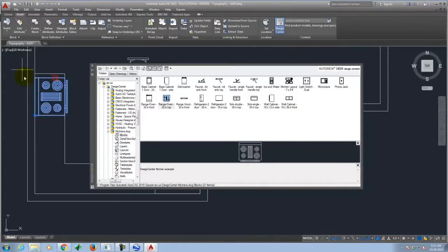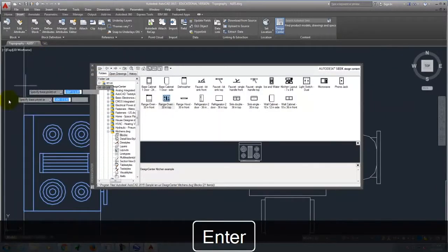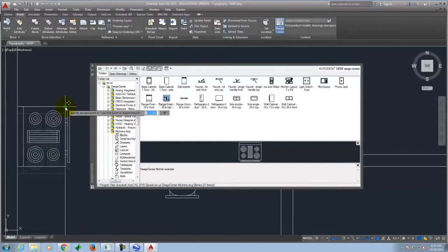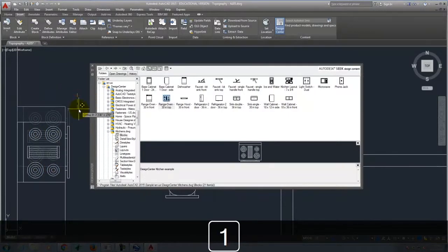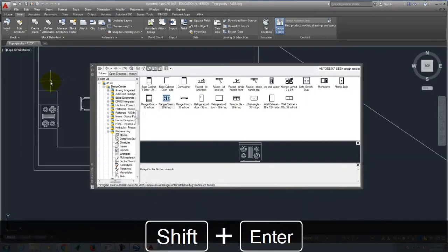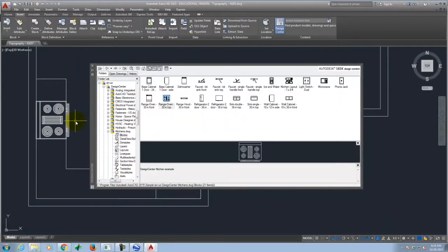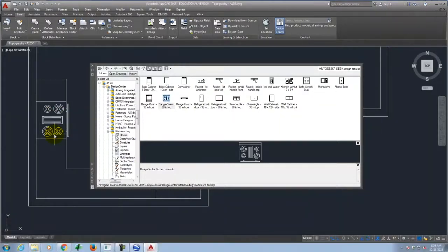Right? So let's say that I want this to be down a little bit further. Let's move. And we'll put it there on the corner. And then I'm going to select it again, type move. And we'll go maybe this way by 18 inches. Something like that. Okay? And so now I end up with the stove that's there. Now, I will say this is not exactly the most attractive stove in the world. Okay? But it's what's built into AutoCAD.